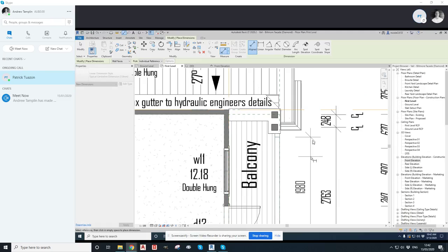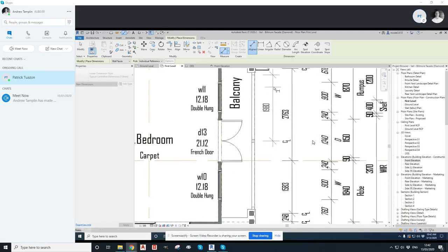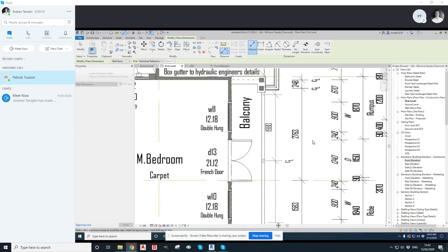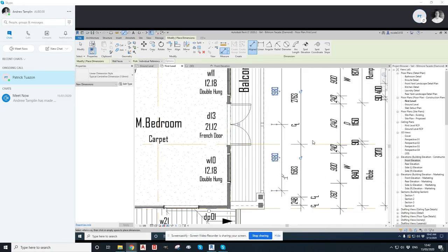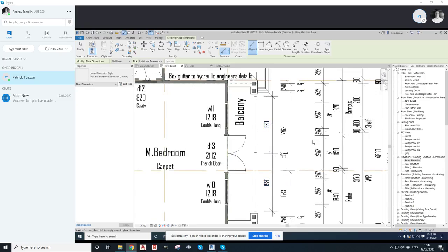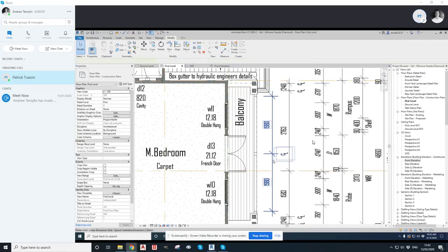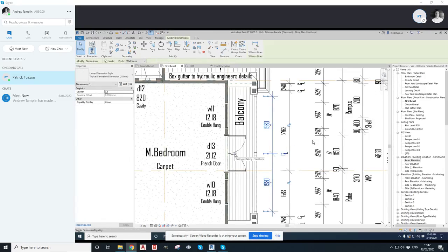And then go down. Do the same thing to that post. Click out of it. And then see that EQ? So click back on the dimension. What that does is automatically center the post. It was already centered anyway, so that was a pretty good guess on your behalf. So now you know that post is in the center.